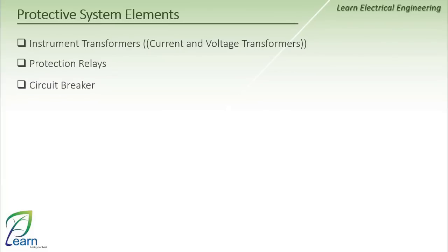The circuit breaker uses the trip signal from the protection relay and disconnects the circuit to isolate the faulty part from the rest of the system. The last thing is the DC supply, which is used to power the protection relay at the station with a voltage of 125 VDC. Here, the protection relay is meant in addition to powering the control relay.